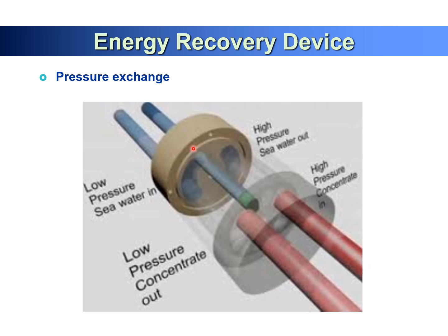and then the seawater comes in, and this pressure will push this seawater, and then this goes to your RO influent, and this will transfer your high pressure to the seawater feed water, and then you can save your energy. So this is the way we can reduce our energy cost.